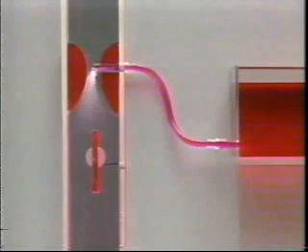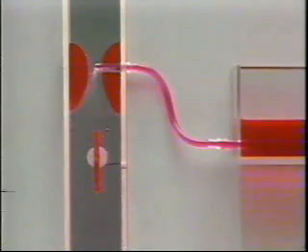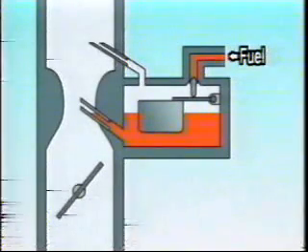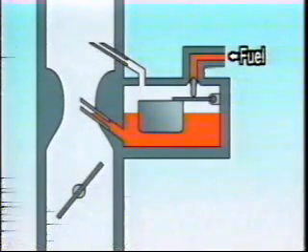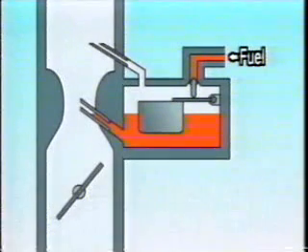The venturi determines the amount of fuel that is drawn in and mixed with the air. However, if there is any variation in the height of the nozzle from the fuel surface, labeled H in the diagram, there will be instability in the air-fuel mixture. So, the float system was devised to maintain a stable level of fuel in the float chamber, which prevents changes in the distance between the nozzle and the surface of the fuel.